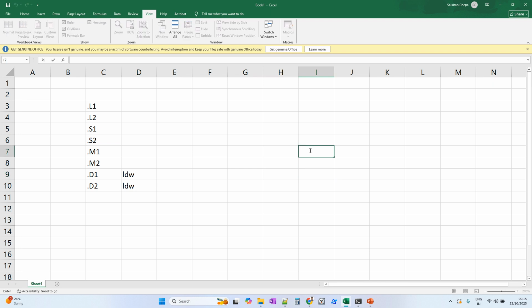Okay. Here we will do the multiply. MPY for lower 16-bit values, MPYH for higher 16-bit values. So next, here we can do the next load, right? Next load, next unrolling we are doing here. So second load we can do, LDW2 we will do. So this will come here, MPY2, MPYH2.